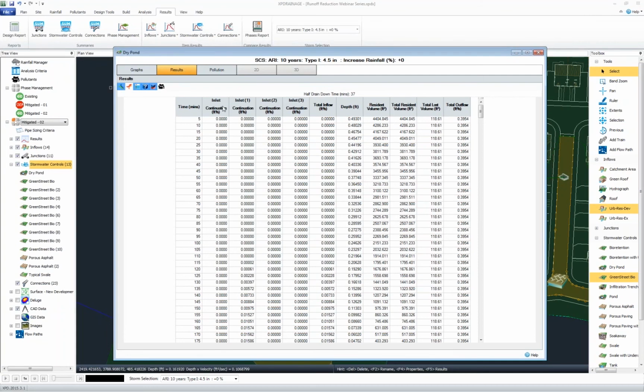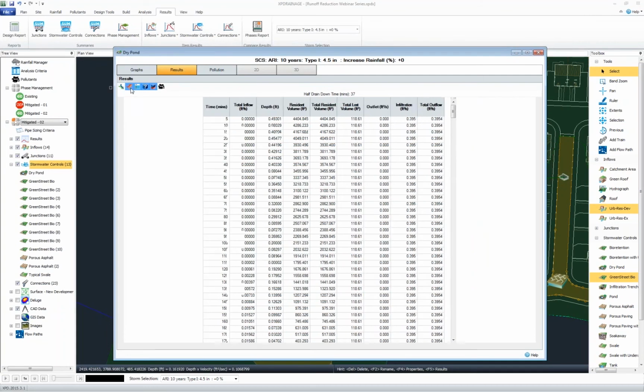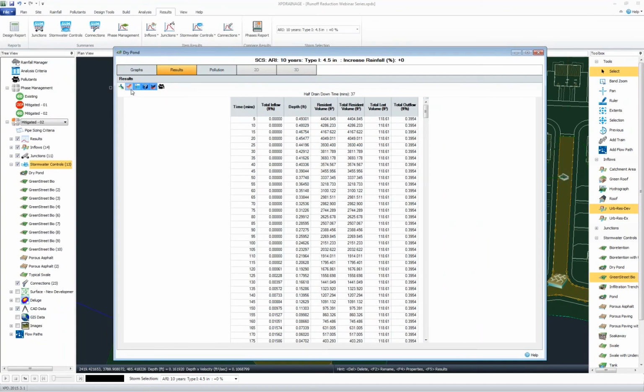You could look at each time series. You can also look at that outfall, if there's multiple outfalls of that. Really as complex as you want to get, we can dive into. You can see a time series. This started wet. This pond was half full. That's why there's outflow initially. And then we begin to have flow into the system, and then it continues to drain out.